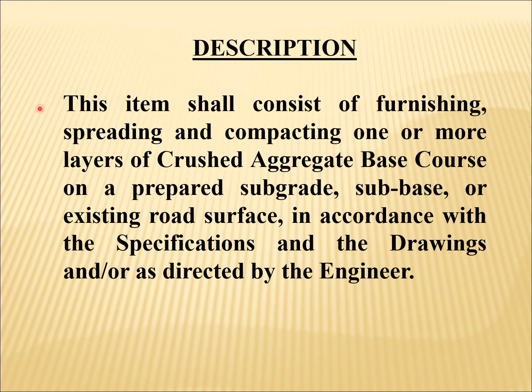This item shall consist of furnishing, spreading, and compacting one or more layers of crushed aggregate base course on a prepared subgrade, subbase, or existing road surface in accordance with the specifications and the drawings and/or as directed by the engineers.